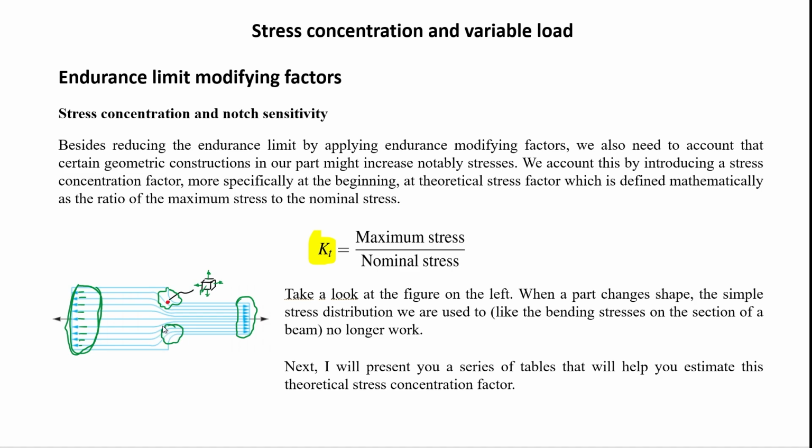Very simplistic kind of explanation. It doesn't describe the full complexity of the topic, but let's take it anyway. It's like putting the same amount of water through a diameter reduction. For sure, something needs to happen there, and what happens is an increased stress at certain points, and that gives birth to the stress concentration factor, which is the relation between the maximum stress and the nominal stress, but of a point, not the whole thing, of a point.